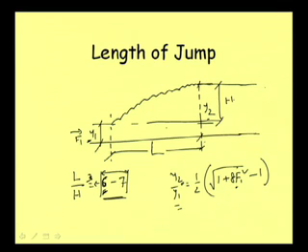Now, when we are conducting the experiment, or in a real field when we find a jump, we cannot definitely say it will be exactly 5 or 6. But if we want to know to what extent the jump will go, then based on these experimental data, some standard curves are available which give us an idea about the length height ratio based on the Froude number.